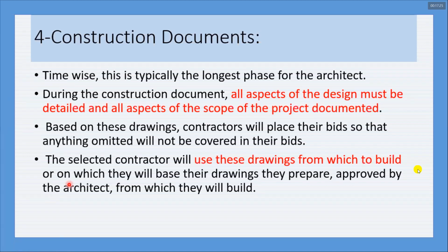Then the construction documents. This is one of the longest phases for the architect. All aspects of design must be detailed, and all aspects of the scope of the project should be well documented. On the basis of these, contractors will place their bids so that anything omitted will not be covered in their bids. So if you miss any detail in your drawings, the ultimate effect is the contractor misses that in the bids.